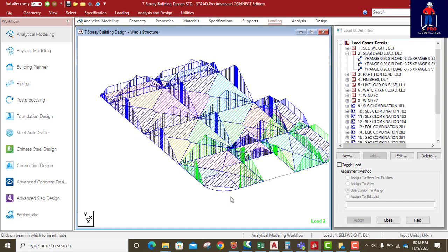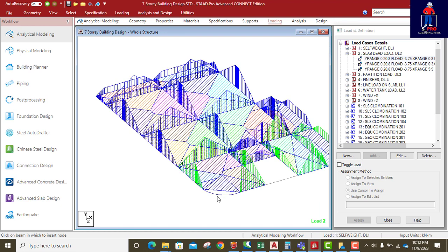So now there's a way forward. There is an option that we can explore, and that is you need to create nodes around this curve and use our normal add beam icon to create the curve. Simple. And that way the beams we have here will just be normal beams like others, and they will take any type of load we apply on them, and we will not have that error. You get? So we are going to practicalize it immediately.